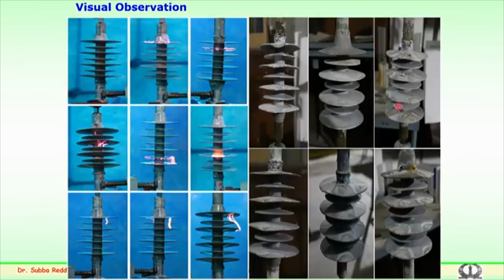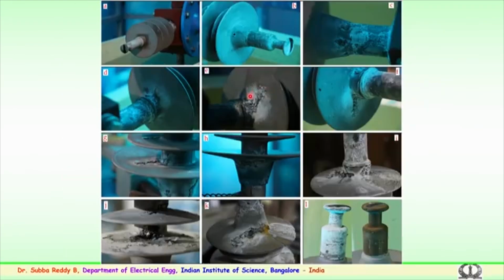In some of the cases you see surface roughness or degradation of the surface, in particular under acidic conditions which are not standardized. The surfaces showed punctures, corrosion on the end fittings, and drastic damage near the fiberglass rod. The entire shed gets damaged, with changes in the color of the sample surface. Several of these phenomena were noticed for both AC and DC conditions.